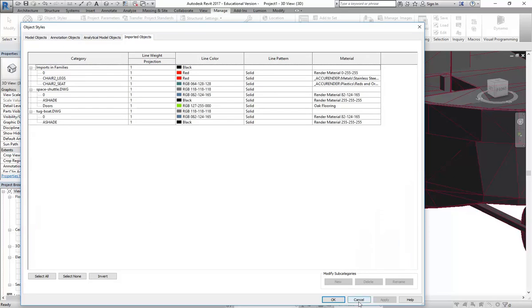If you're wondering how to assign parameters to these, you have to do one extra step, which is to set up the imports in a family. So you import the AutoCAD file into a separate family file, then bring that family into your project. And that's if you want to use parameters. Yeah, that's something to try later maybe, once you've got this far.